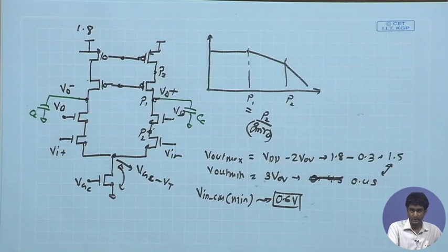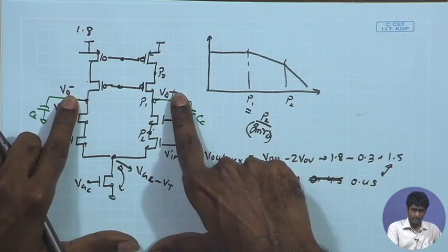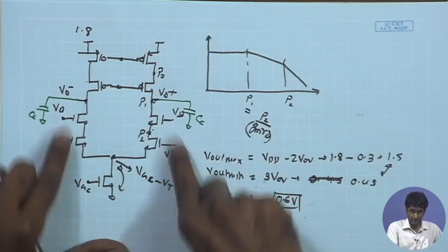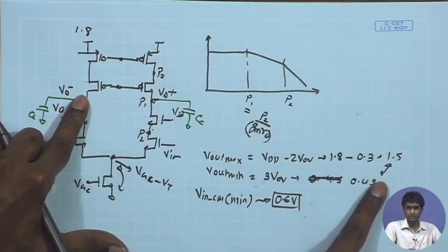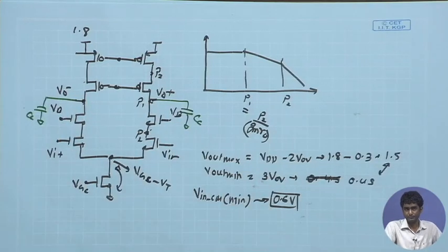On the other side, the negative points that you have are the limitations on output swing, and more severely the input biasing. How will you use the output DC common mode for maximum symmetric swing to bias the input DC? There are some other advantages also, like we have discussed the concept of PSRR, power supply rejection ratio. There the cascode devices do have an advantage as compared to our two-stage op-amp, that we have not discussed in detail. Probably in one of the classes we will try to address that as well.